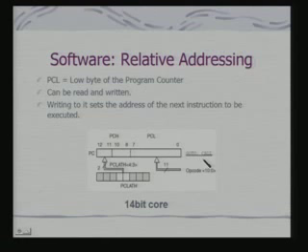Now, you have got relative addressing and software relative addressing as well, because when you are doing any of these goto and call, what is the significance of the fact that the most significant bits are coming from the PC latch high register? It means all your goto and call are in a sense PC relative, relative to the current PC value, because for the current PC value, the most significant bits are loaded onto PC latch high.